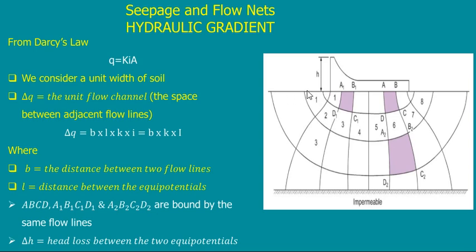I have here the first equipotential line. My second equipotential line should be here. I try to choose the location of this line so that I can put a circle in this location. If I manage to put a circle, then my choice for the line is okay. I have to take many things into consideration. First thing is that these angles are right angles. Here right angles, here right angles, here right angles. They should be right angles. At the same time, I can draw a circle here.